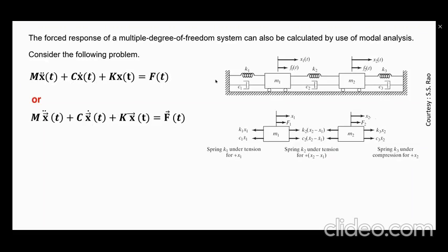You go back to a single degree of freedom, look at the free body diagram, mass x, and the acceleration, etc., and you get this equation. So literally, you should be able to sit down and, based on the diagram here, come up with the mass matrix, stiffness matrix, and the damping matrix.